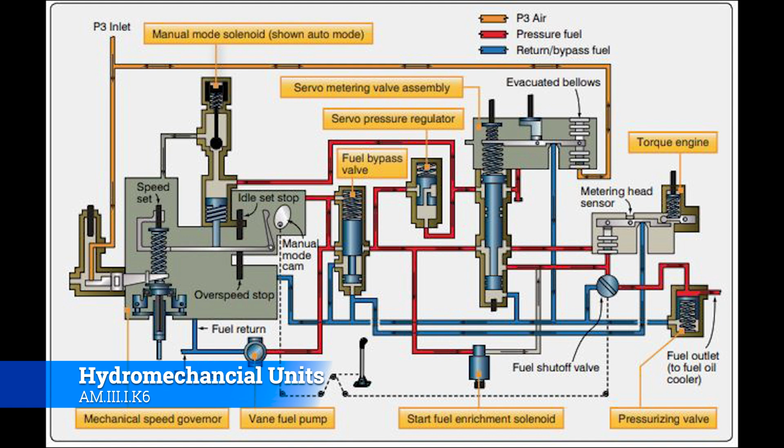So if you look at the graphic, you'll see that a lot of this is air driven. This goes back to using huffer carts to spin up turbines. And it's not just moving the fan blades, but it's also supplying pressurized air to those old mechanical or hydromechanical units to actually operate and work.